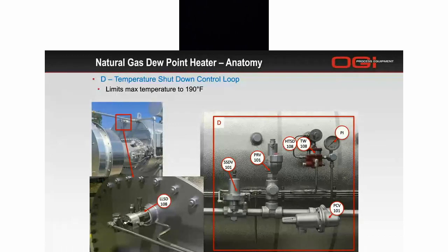On the left, you can see a zoomed out and a zoomed in view of the level switch. So we have a level switch at the 12 o'clock position on the end of our heater. And you can see a zoomed in view of it here. We call it a switch, but it's not an electrical type of switch. This is a pneumatic switch. Electrical ones are available for electrically controlled systems, but again, this is a pneumatic example.